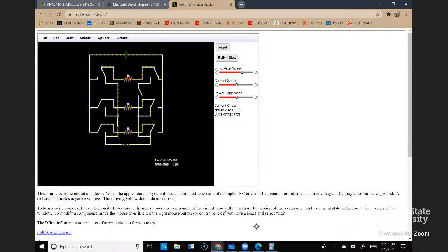The power through these two is going to be 2.78 milliwatts, which is exactly what we predicted there as well. So you can see the power of being able to figure out analytically, as well as just looking at the currents through each, how much power is dissipated through each resistor, assuming each resistor is identical, which we do.